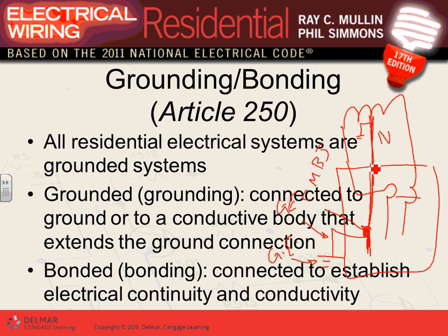So what they want you to do, very simple, guys, without getting into the terminology, two things when it comes to the service. Here's my service right here, here's my neutral. Number one, they want you to ground the neutral, very important. Then they also want you to ground the box. That's what bonding and grounding is all about. Grounding the box, that's the equipment, and grounding the neutral. That's what you do at the service.